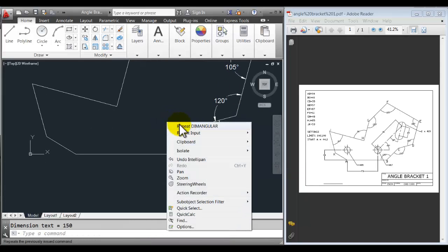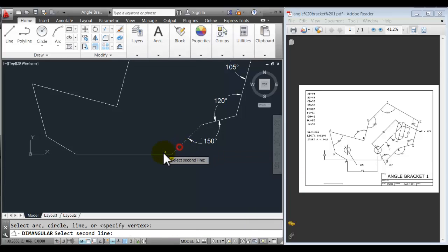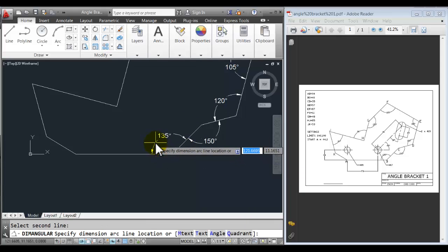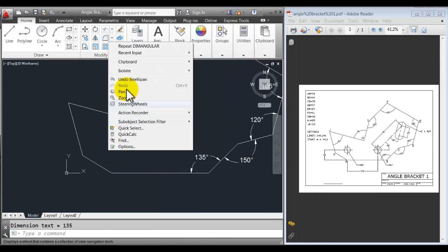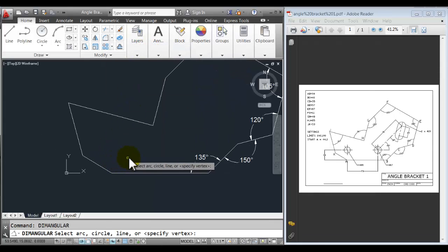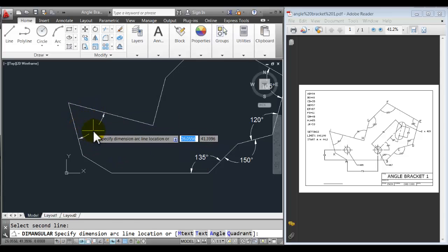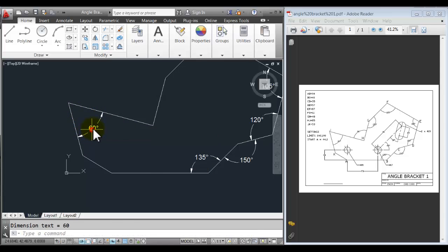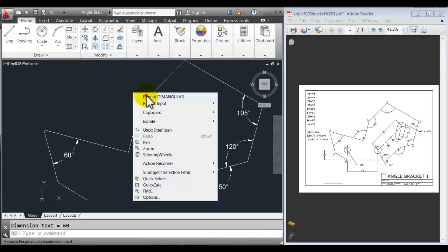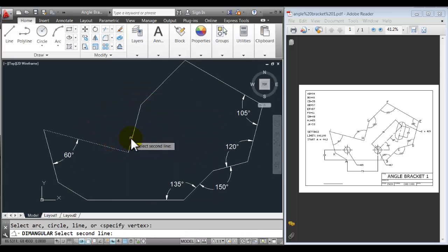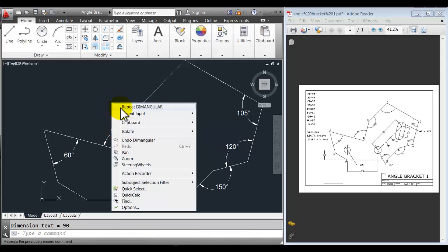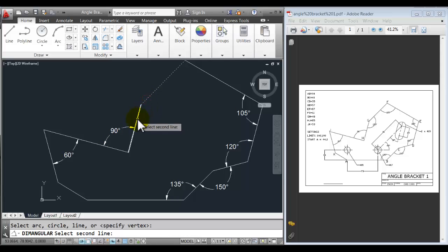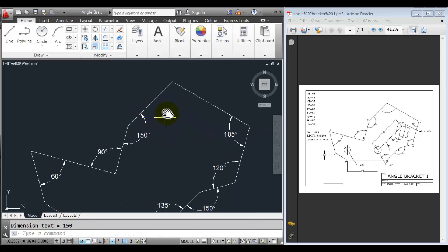Now, if you think that that number, the 25.4, is too big, and you want to change it later as you're working with this detail, and we actually might end up doing that, you can always go back, type in D and enter, pick the Modify button, go to the Fit tab, and change the overall scale there. So looks like our numbers are all correct,